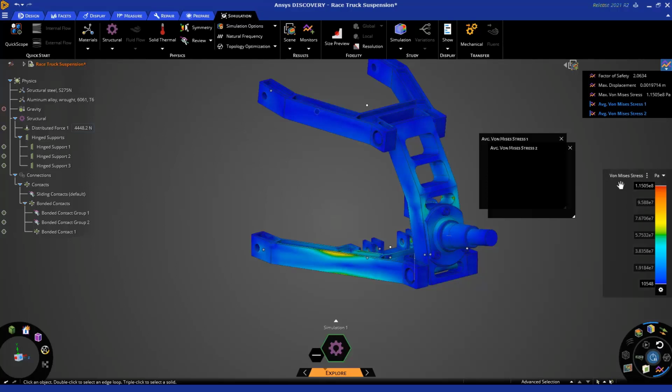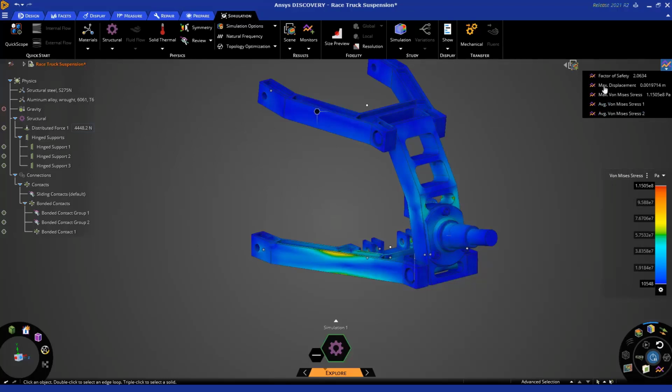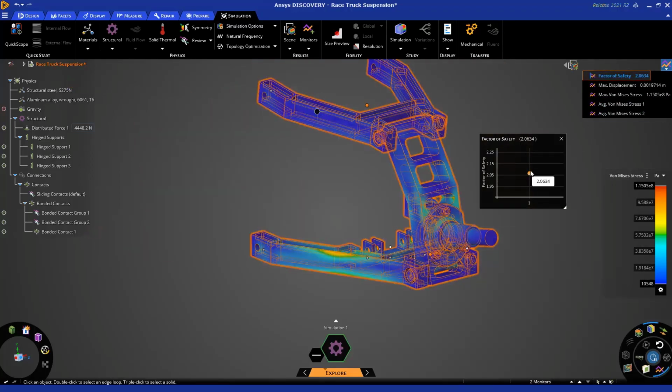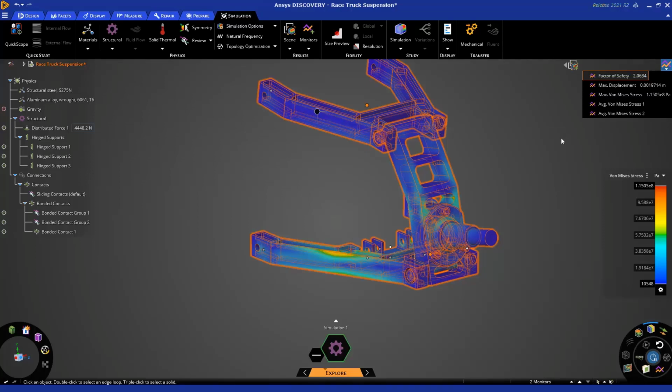So as you can see up here on the top right of our screen, we have these charts, and if you wish to display them, you can go ahead and click here and then choose to see your current design point. So this is a singular design point. If you change the value of one of your variables, this could be related to a geometrical change, changing the shape of the object, changing materials, or changing boundary conditions. Any change to this environment will create a new design point.